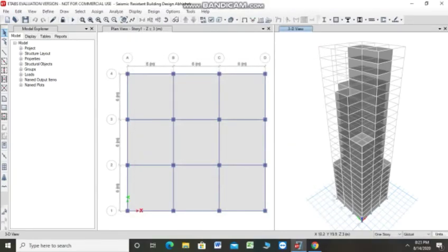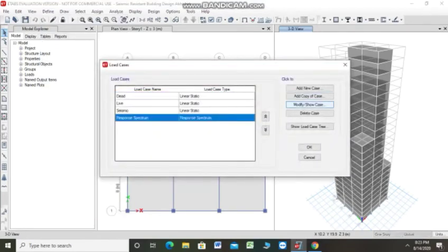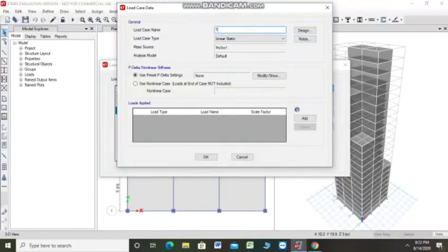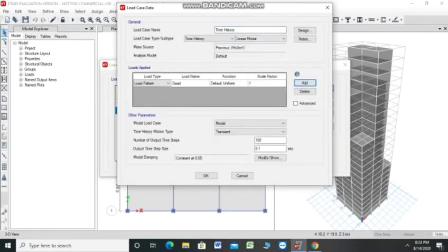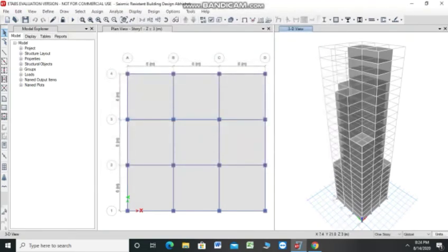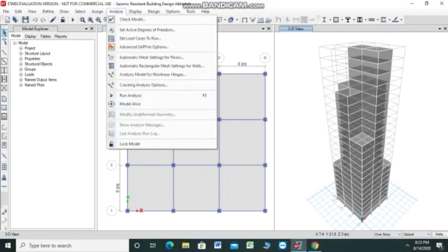Then we will move on to the next load cases. So we'll delete the previous one and add a new one. The new one is time history, so time history only one. This one is right here, U1. So load type is acceleration. We'll type the scale factor as before, 166345. Okay, this has been assigned here.